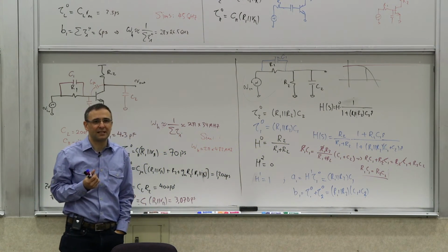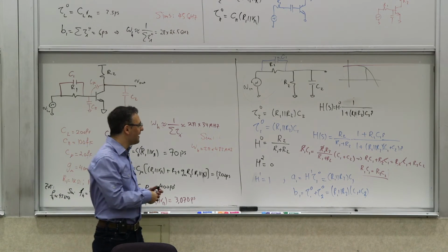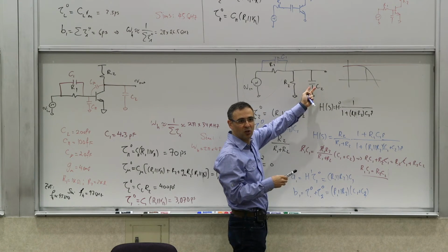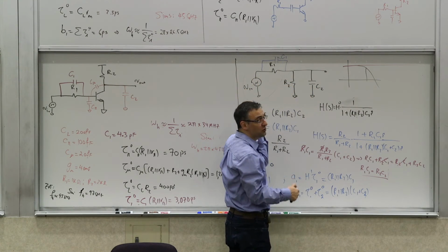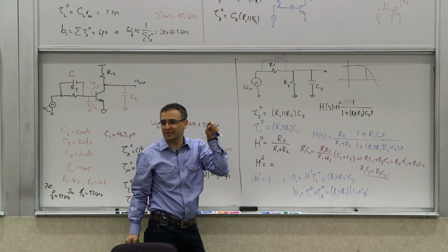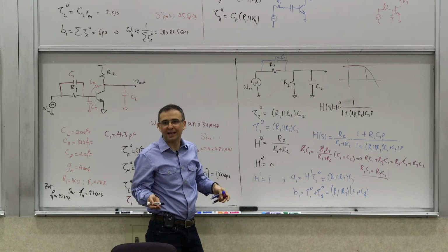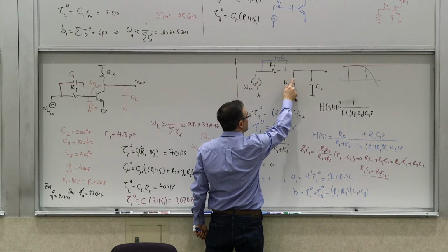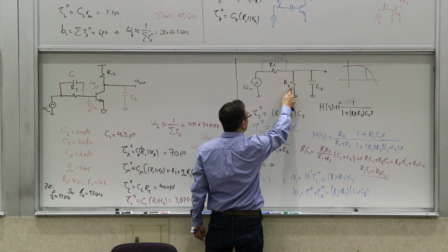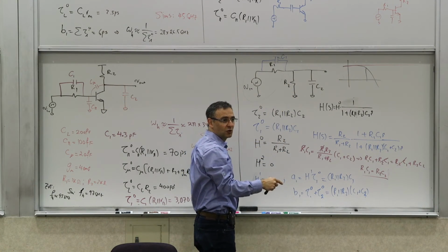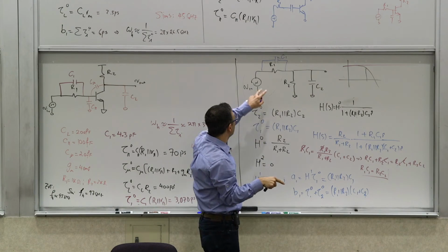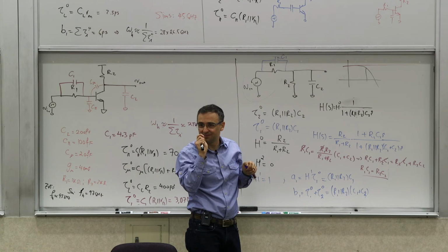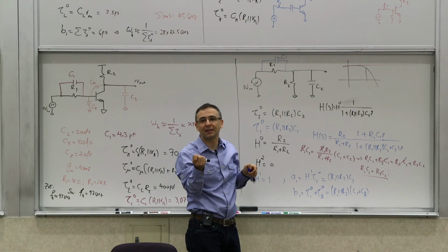Basically what it is, the input of the oscilloscope looks like this, right? So you can try to connect it directly to whatever your source is that you're trying to measure, and then you will get a low-pass response. Or you could introduce an extra resistor. In the case of a 10x, they make it 1 to 9. So it's 10x attenuation. But then you add an extra capacitor, and you're making it balanced out.